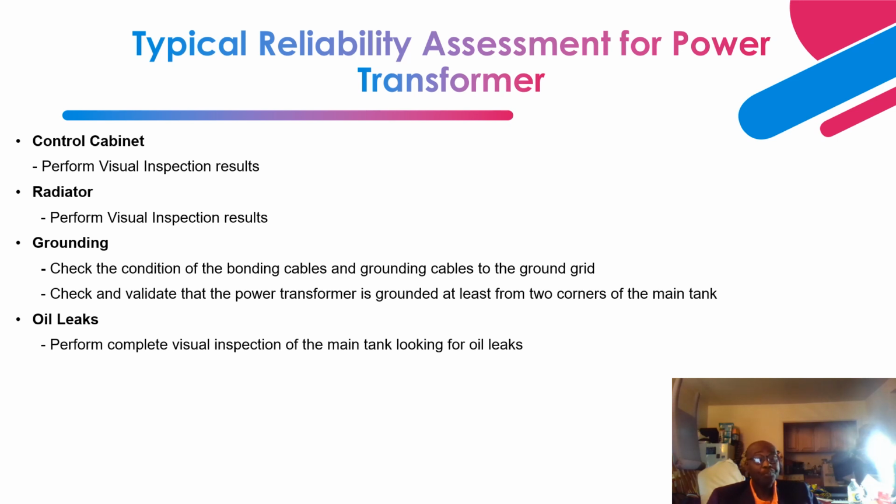And sometimes, the drop rate of the leak can be noted. Let's say every second, every minute, you can note that leakage rate and put it down, and also note the location by just a sketch of where the leak is located, so that it helps with planning. Let's say if an upcoming major outage is coming up, you can arrange. If it is a major leak, you can arrange for that leak to be fixed.